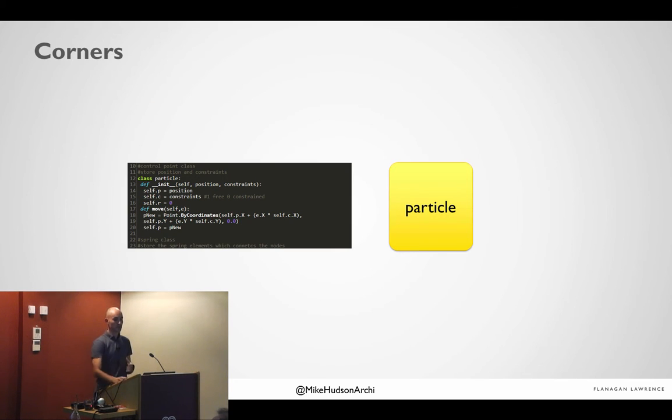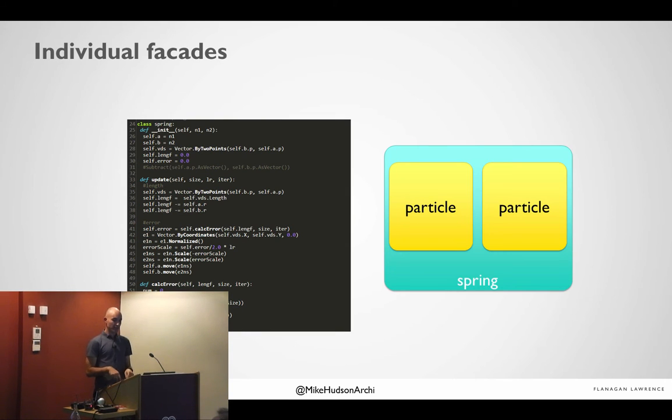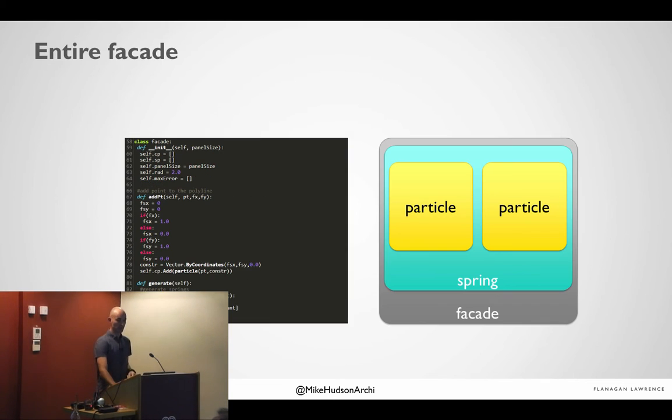And for us to optimize it, we created something called a particle spring system. So we define the particle, that's the corners, 7 corners. Then we say, okay, between every spring, so every length of facade, there are 2 particles holding them. And then the facade is basically contained between all of those 7 springs. So if you move one spring, that has an inherent effect of moving all the other springs around the circle. So you essentially create a 7-dimensional problem.